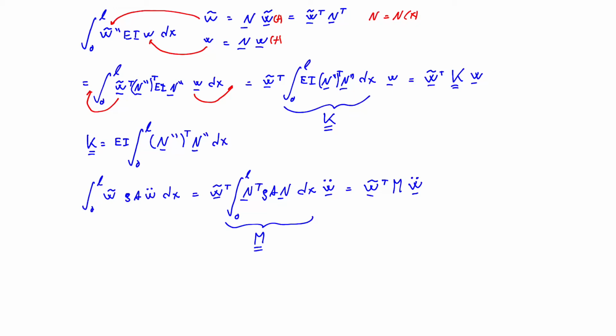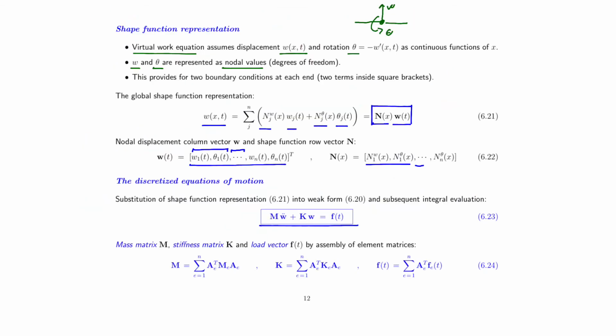So both the stiffness integral and the inertia integral will have the transpose of the test function in front as the first factor, whereby it will appear as a common factor on all terms. The test function cannot be equal to 0, therefore everything within the parenthesis should be equal to 0, and that provides us with the equation of motion in its well-known form in 623.